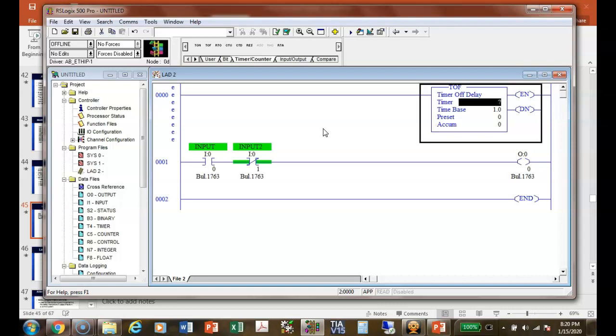What this does is we specify an input, we specify a slot number, and then we specify which bit within the slot we want to go to. So we have to understand binary to even understand what I just said. So very easy to address. But watch what happens if I assign it a name.